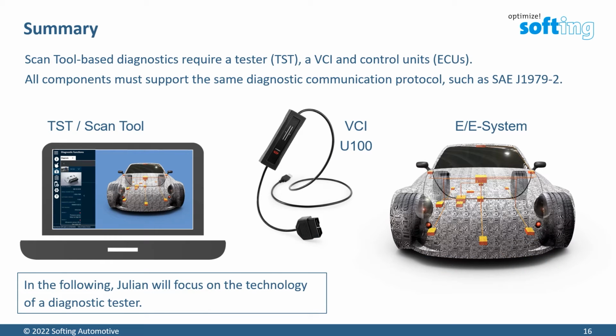With my almost last slide, I would like to summarize my presentation as follows. Scan tool-based diagnostics require a tester, a VCI, and control units. And all components must support the same diagnostic communication protocol, for example SAE J1979-2. In the following, my colleague Julian will focus on the technology of a diagnostic tester.